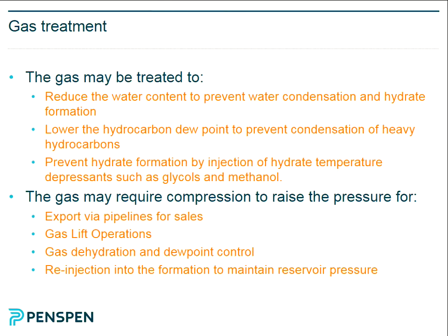And gas dehydration. This is a bit busy, but this connects to the other chart I showed you. This is the connection from the low pressure separator, medium pressure separation, and the high pressure separator, but the other way around. You're starting with a low pressure and going to a high pressure. So you get the gas from the low pressure separator. You may cool it, and then it goes to a knockout drum. If any further liquids dropped out of the gas, you can knock those out, and then you compress the gas.